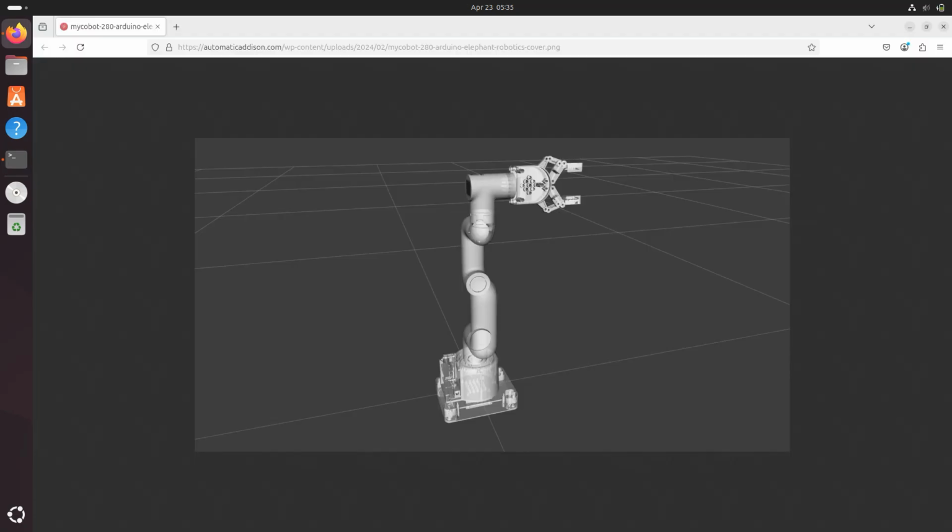Now let's create our URDF file. We will actually create it in XACRO format. I will use the terms URDF and XACRO interchangeably going forward. Remember, XACRO files are like blueprints for URDF files, using macros and variables to simplify complex robot descriptions. Imagine XACRO as the architect drawing up plans, and URDF as the final, ready-to-use construction document.